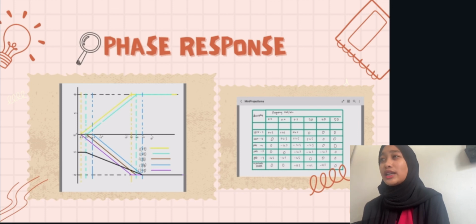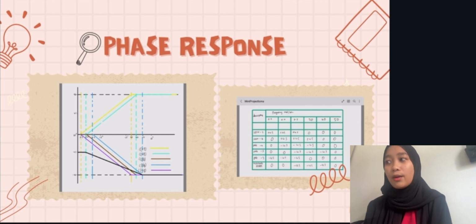Before we get the equation for the amplitude response, we need to replace the s with j omega and get the equation. Then the equation for the amplitude is 20 log something, but for phase we do not need the 20 log form; we need to change it to the degrees form.